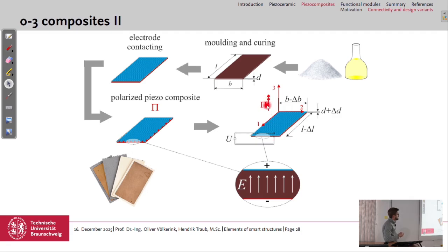Our polarization direction is in the direction of the field, but with surface actuators or transducers we would use the in-plane elongation, the in-plane strain of the material. So what effect would this be?